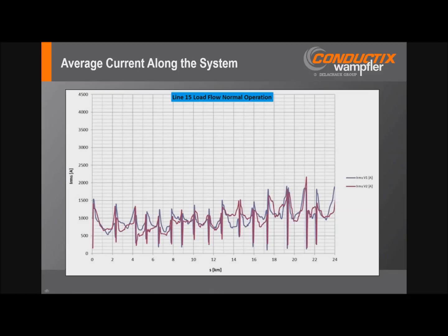What about the gaps and expansion joints? Did we follow the recommendations that you said earlier? The gaps and expansion joints, one thing I didn't mention is during installation, these need to be set based on temperature. So we take the ambient temperature of the conductor, we go to a gap chart that's based on the total range of expected movement of this, and that expansion gap is set.